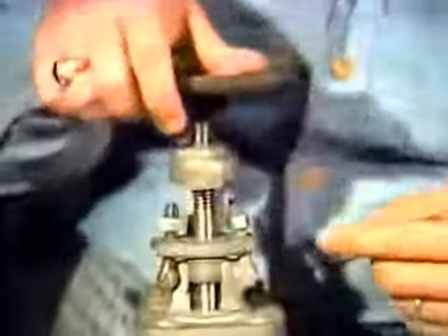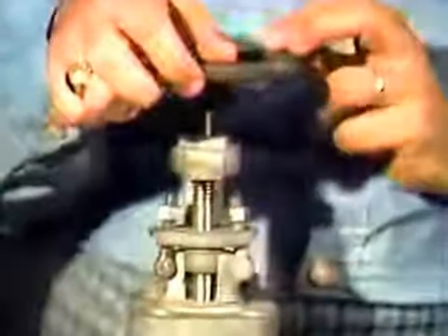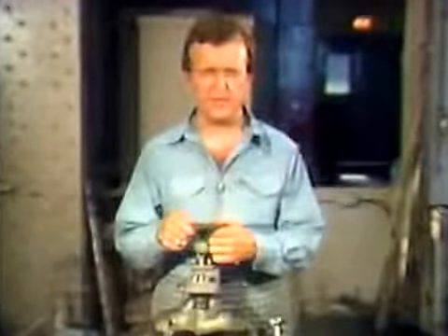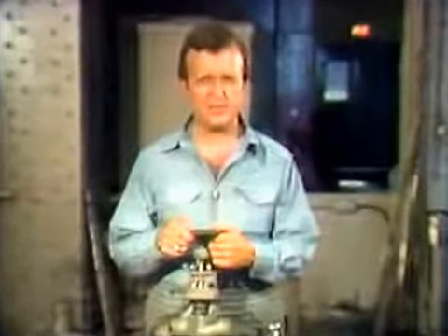Globe valves are usually made with a rising stem, similar to the rising stem of the gate valve. The stem is threaded into the bonnet or yoke bushing. Like gate valves, the specific function of a globe valve determines the material used to build it. You'll find more information on the types of globe valves and how they're made in your text. The preceding types of valves are good for high pressure and high temperature. The following valves are used for low pressure, low temperature applications.